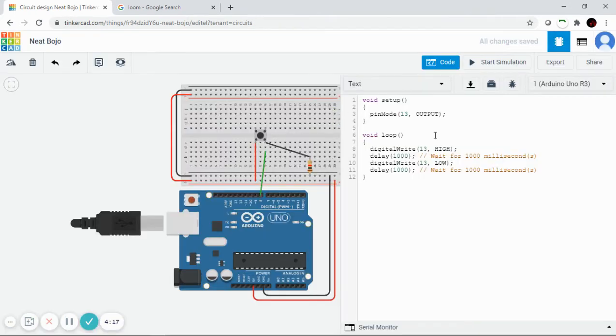Okay, I'm going to remove all this initial stuff. First of all, we need this digital pin to be set as an input for taking the value from the push button to see what happens when we click it. So we set pinMode pin 8 as INPUT, semicolon.